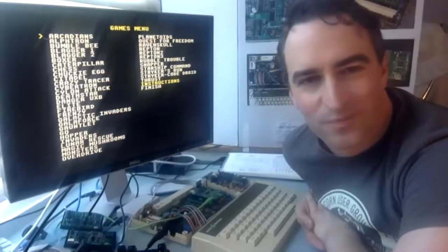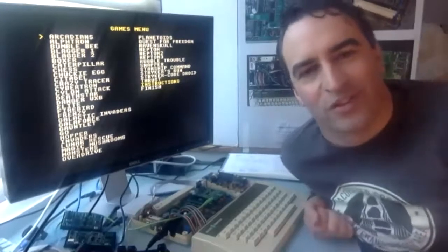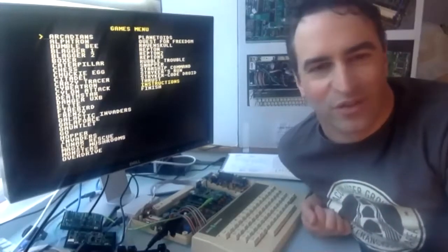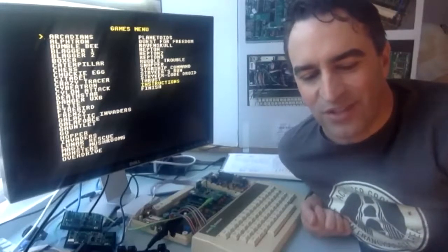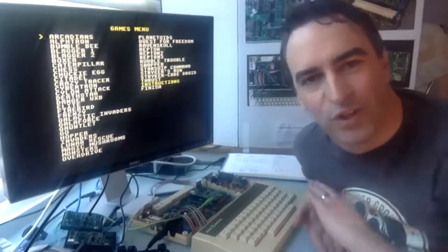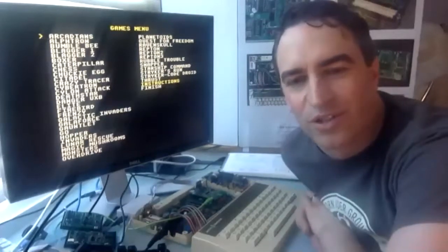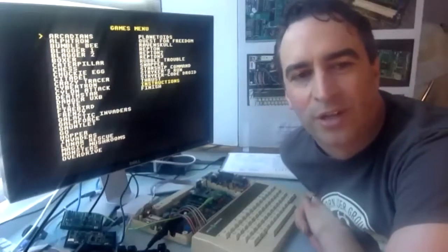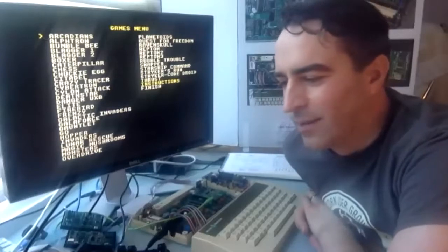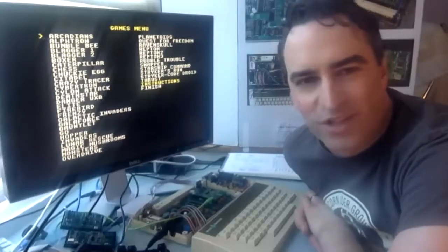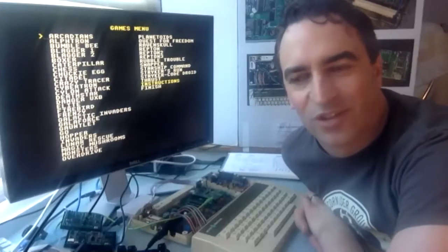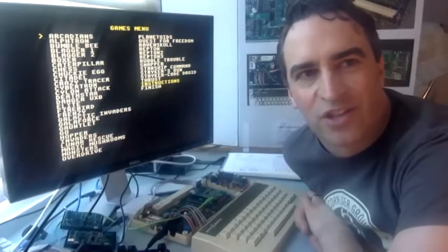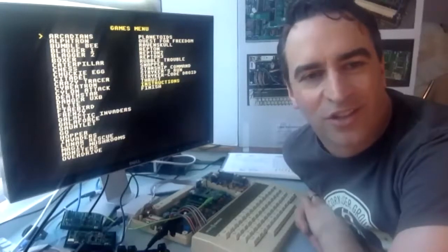For people who aren't familiar with this, Verilog and VHDL are languages with an enormous number of features, most of which you can't use when you're trying to design stuff that works on actual hardware. But if you're just doing it for simulation and testing, all of them are quite useful. You can do things like set this signal to 1, then delay 2 nanoseconds, and then set it to 0.